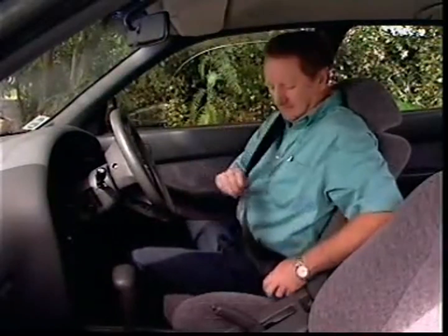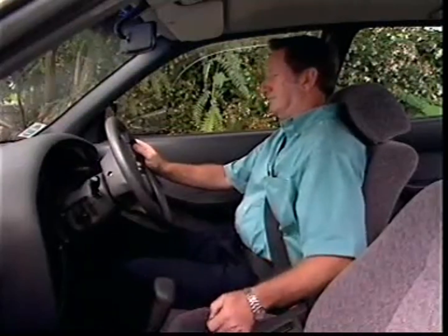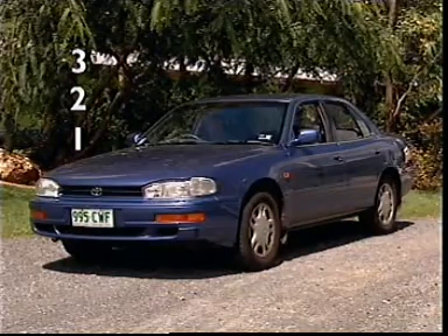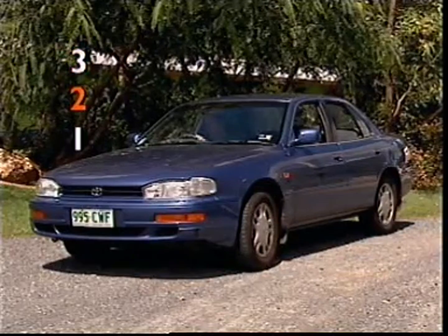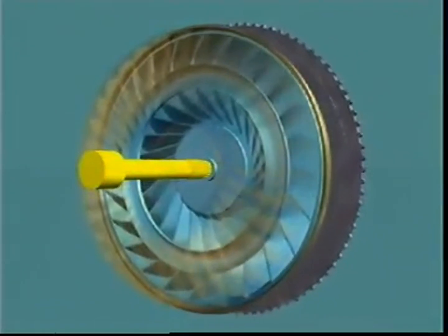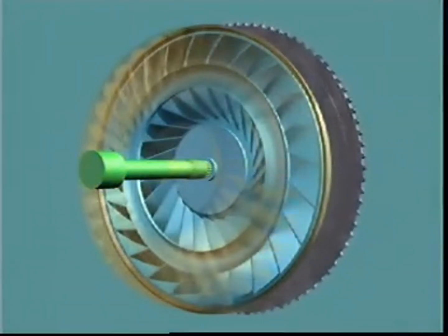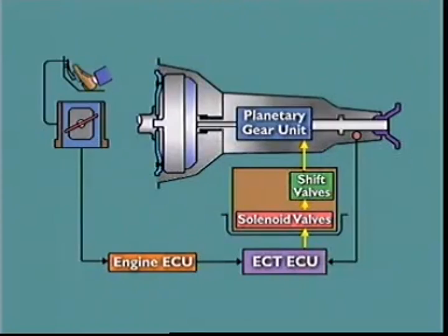It will also select the best available ratio for a given condition, which improves fuel consumption. Anti-squat control can be provided when the transmission is placed in a drive range from the neutral position. The transmission will engage second or third gear before shifting into first gear. The input shaft attached to the turbine is still brought to a sudden halt by engaging a drive range, but the shock is absorbed by successive engagement of the gears.